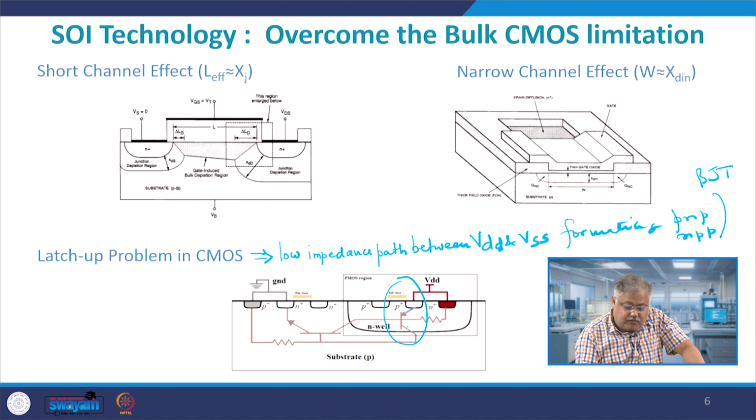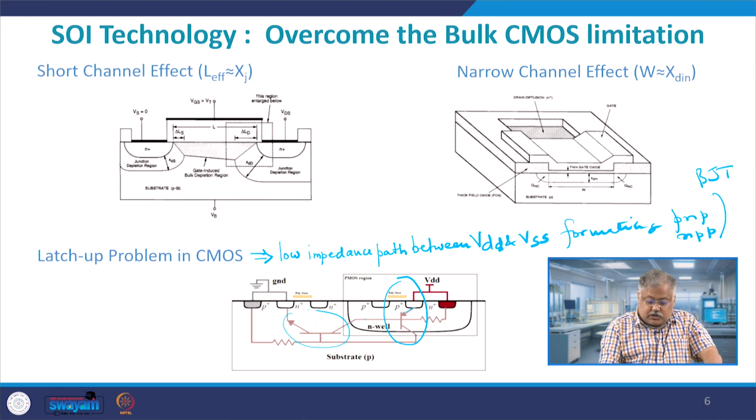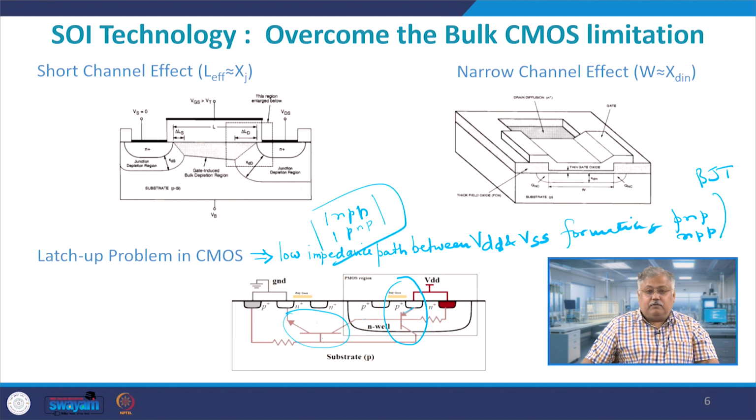So they basically form two back to back coupled PN junction diodes here, and that can be understood as a PNP transistor. Similarly, if you look at this particular point, I have a P type substrate here, I have an N well here. So this is N, this is P, and again I have an N plus region here. So this also forms an NPN transistor. So I have one NPN and one PNP transistor. If you look very carefully, these BJTs actually form a PNPN structure.